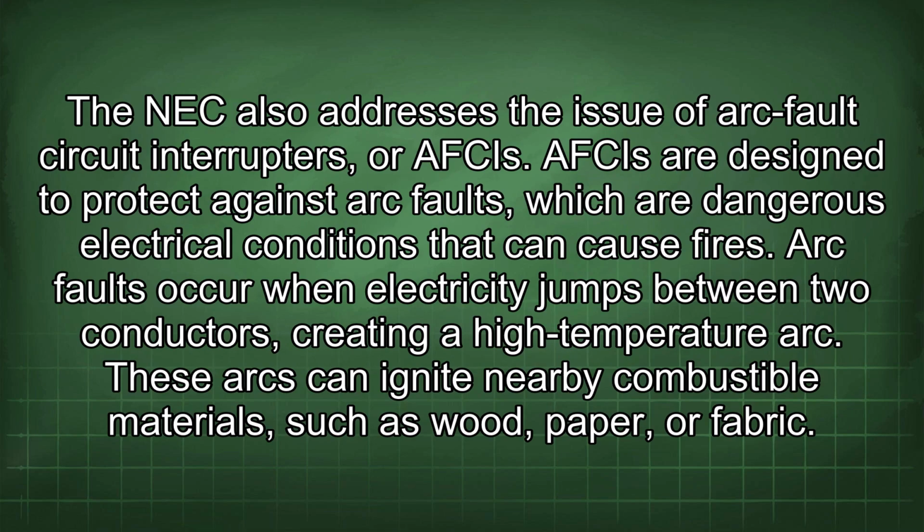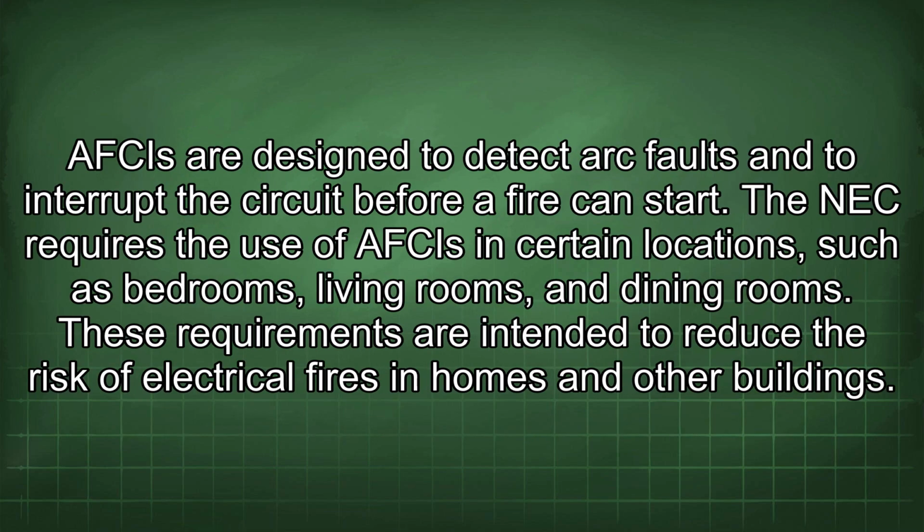The NEC also addresses the issue of arc fault circuit interrupters, or AFCIs. AFCIs are designed to protect against arc faults, which are dangerous electrical conditions that can cause fires. Arc faults occur when electricity jumps between two conductors, creating a high-temperature arc. These arcs can ignite nearby combustible materials such as wood, paper, or fabric. AFCIs are designed to detect arc faults and to interrupt the circuit before a fire can start.